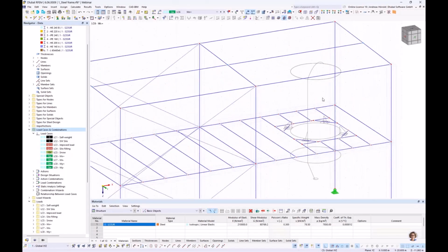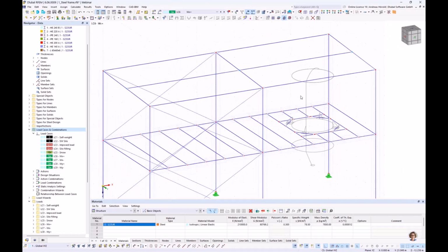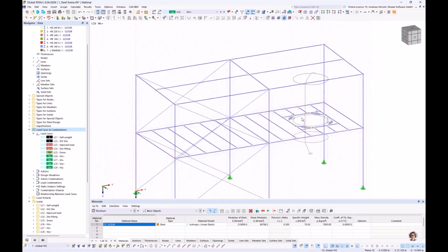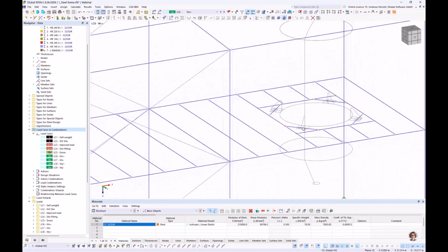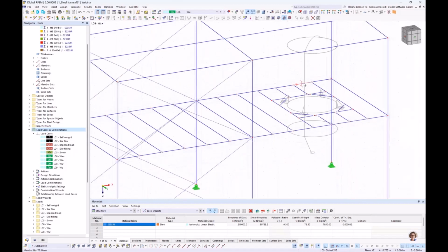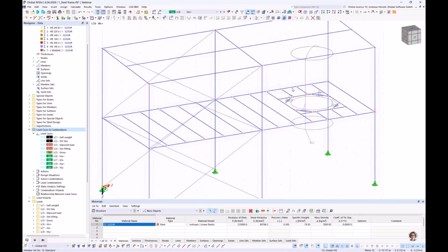That's in that area a doubled load, but I would like to consider also the horizontal load at the beams and also the vertical load from the wind that we get from the moment that we get from the wind on the silo.